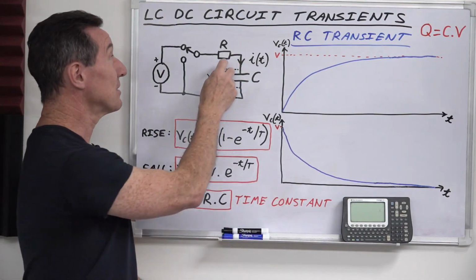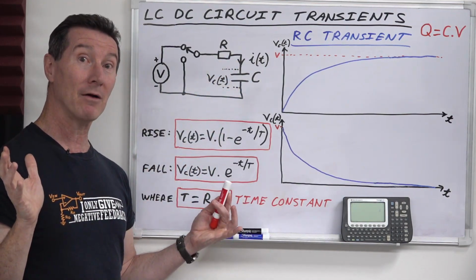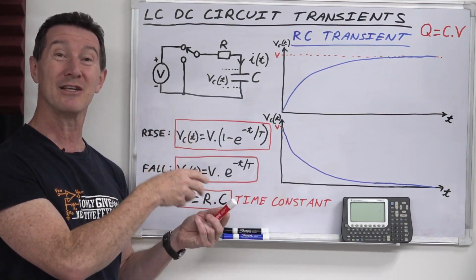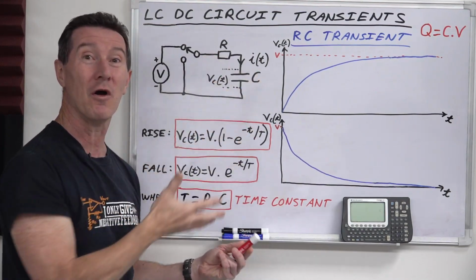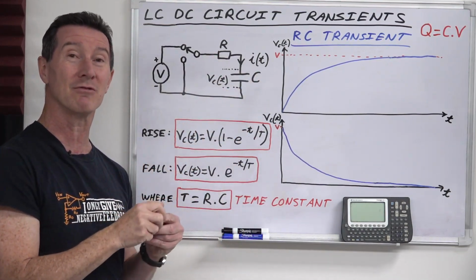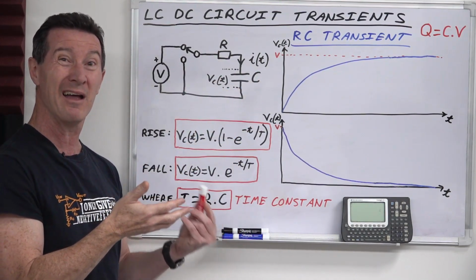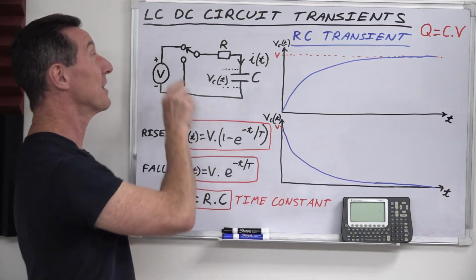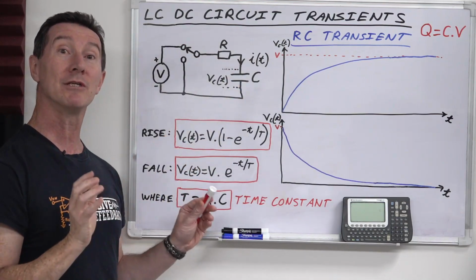And that series resistance in, say, a mains 240 volt power supply, there's really not much resistance there. You've got the connectors, the wires, and then you've got basically the equivalent DC resistance of the diode bridge rectifier, and that's pretty much it before it gets to big thumping capacitors. So the inrush current is going to be very large.